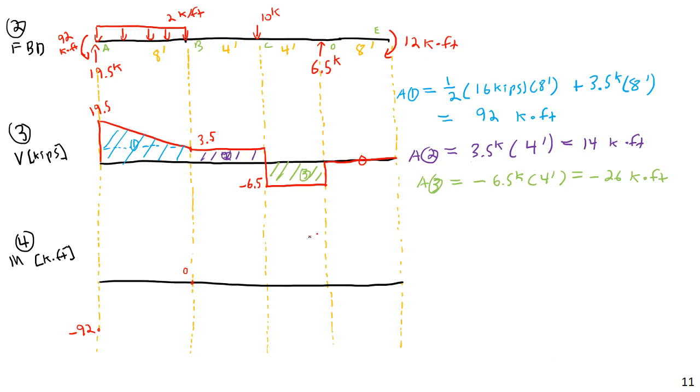And I didn't just start there and assume it. We actually worked through it by the calculation. So we know this is a useful check, just like working your way across a simply supported beam and finding the moment at the end is 0 is a useful check. If we did this and we found that the moment was not 0 at the hinge here, we would know that we had done something wrong.